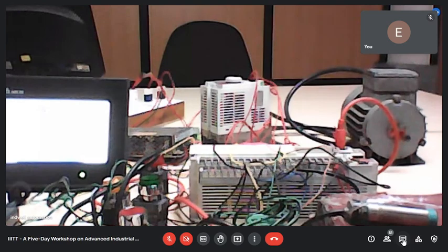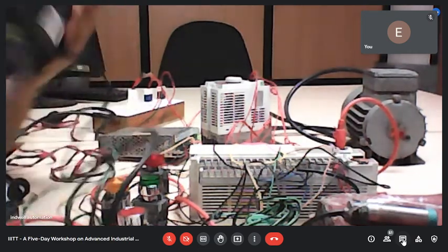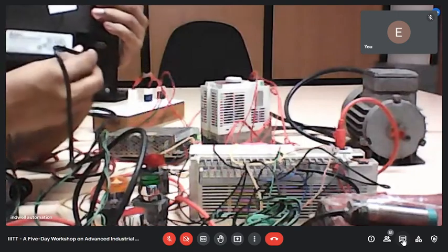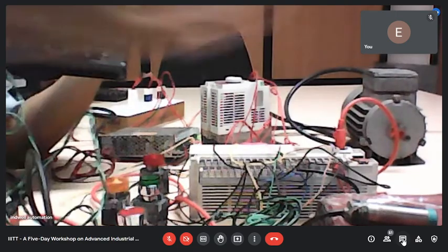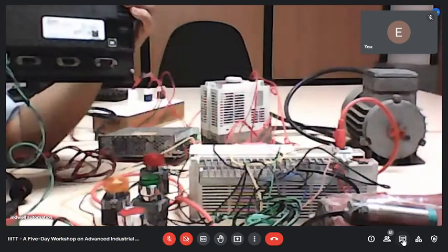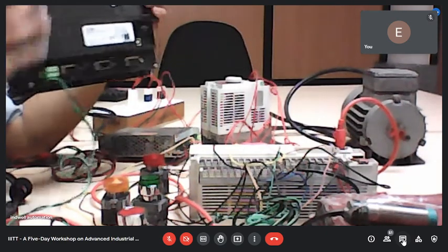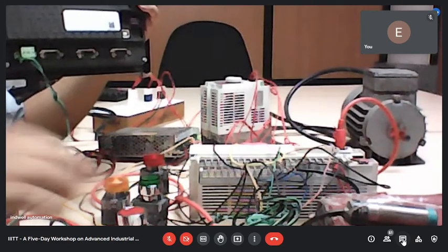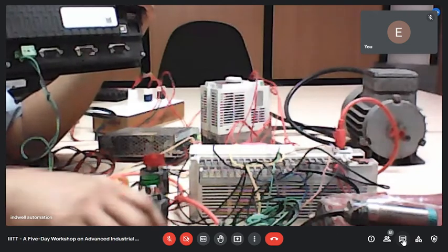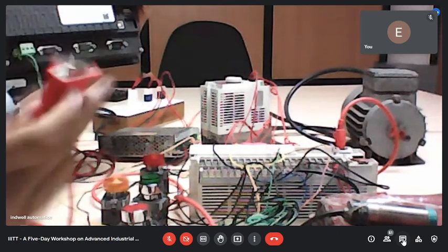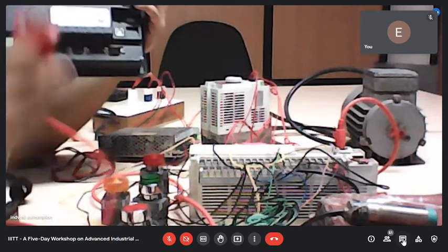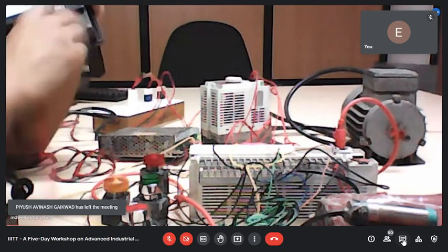So you understood that you connect that communication cable to your PLC, laptop, and send data. You have sent it already. After sending that, you don't need this programming cable, so you can remove it if you want. So I have removed it. Now I have one HMI designed with some program. Now you have to take the normal communication cable you use for your PLC. Yesterday we used this cable, right? Red cable, 9 pin. And here on COM port number 1 also we have 9 pin. I can connect it.